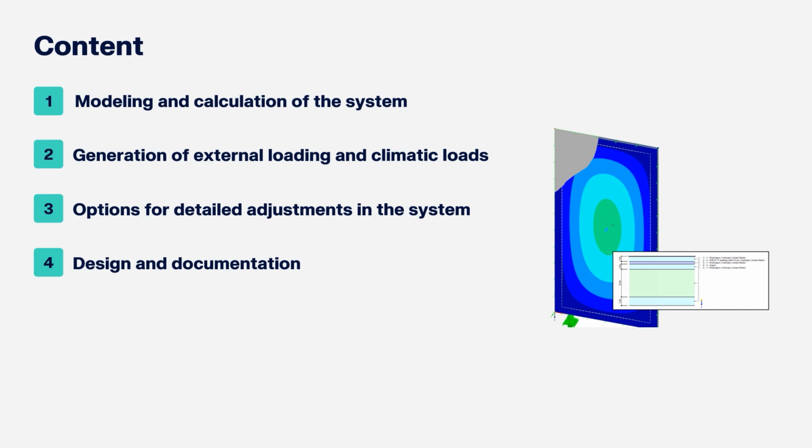Thank you, Andreas, for your introduction. Also from my side, hello to today's webinar. The topic of today's webinar is how I model and design an insulating glass unit with RFEM. I want to show you the modeling and calculation of the system. I want to show you the generation of the loading, the external loading, and also the climatic loads. We can call it the internal loading.